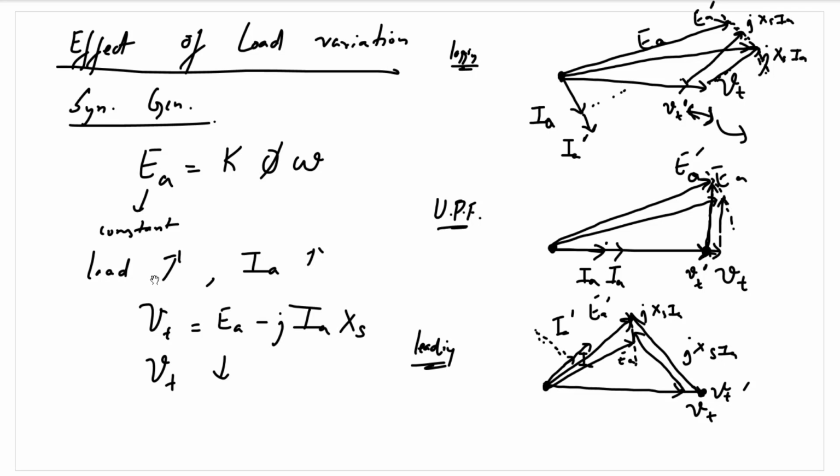So, if we go by intuition, we would not be expecting a voltage to rise as we increase the load. So, the nature of the load will actually determine the voltage at the terminals. That's the voltage available to the consumers. So, for a capacitive load, there will actually be a rise in voltage level at the consumer end or at the terminals of the synchronous generator.